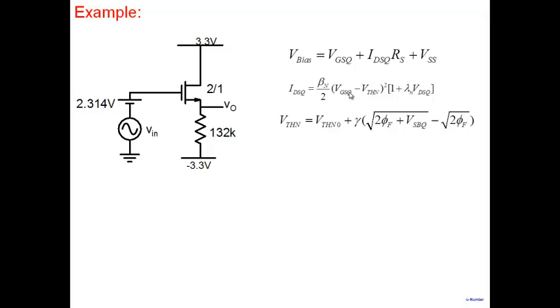So that's why this is easy to do if you have a computer at your disposal. Otherwise, doing it on paper and pen, 1 iteration, 2 iterations, and 3 iterations can become a little bit boring. Conceptually it's simple, but you have to repeat it 2-3 times here. There's no other alternative but to do this. Or otherwise, you can think of substituting the VTHN that you see here, getting one big equation, and you can try and solve it.